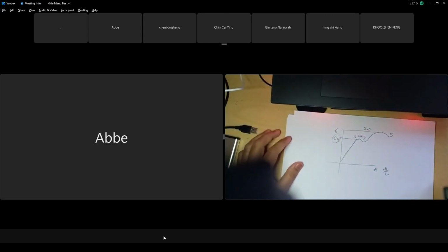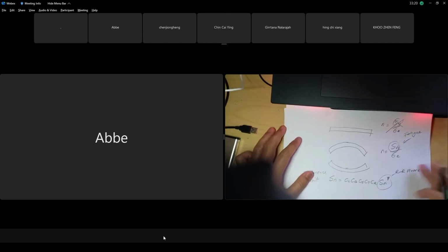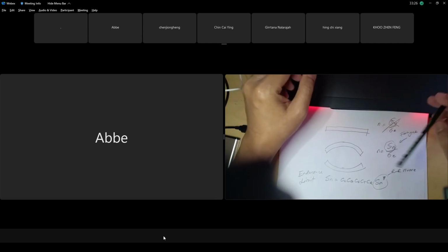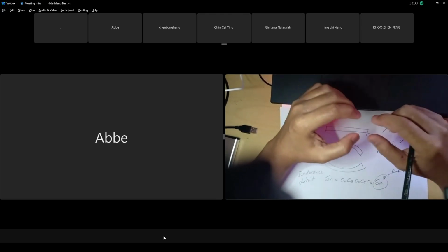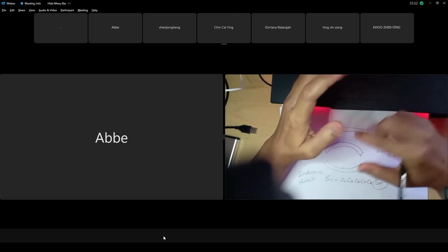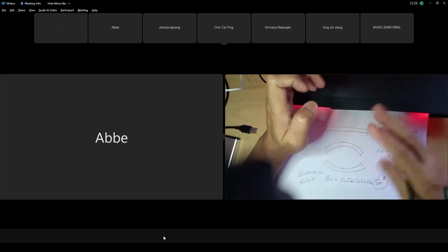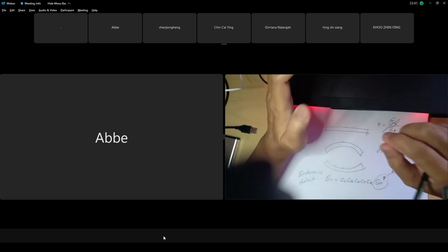That one is for static. But for fatigue, the standard tests are also already done by engineers, using pure bending load. On a standard specimen they do a bending test where the shaft is rotated, and they already put the data.